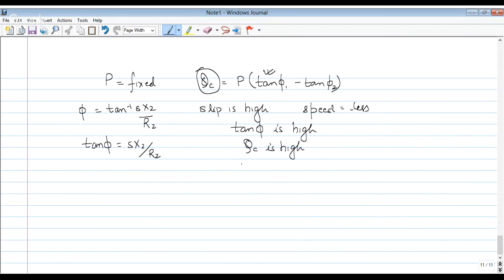And Naveen, the question: before a capacitor start motor reverses its direction, the centrifugal switch is open, the running winding is open, the capacitor connection must be reversed, or is connected to the line. Actually, why would a capacitor start motor reverse its direction? Once the motor has started, it must continue to run in the same direction. So actually, I'm unable to get this question. Why will it be reversing its direction?